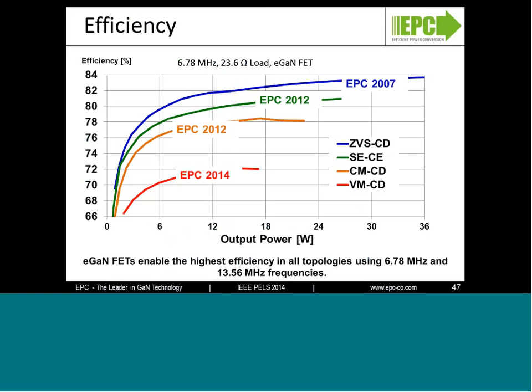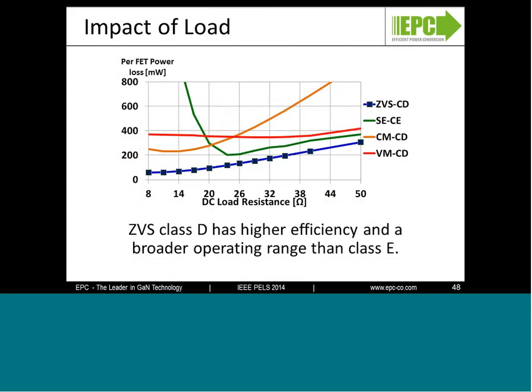Another thing you need to worry about is the impact of the load. Depending on what you're charging, it's going to change that load impedance. And depending on the topology selected, the efficiency can be very dependent upon that load.